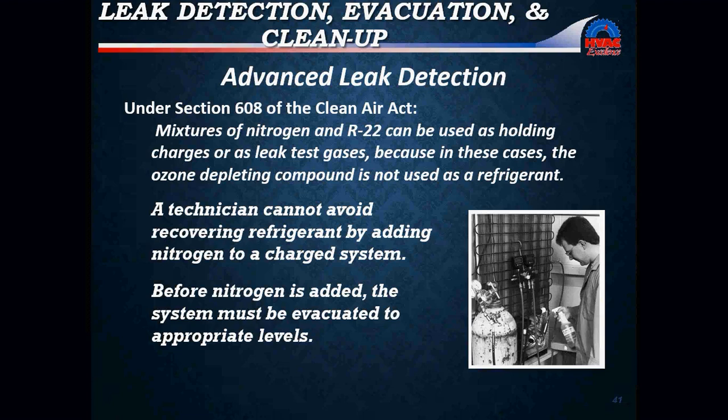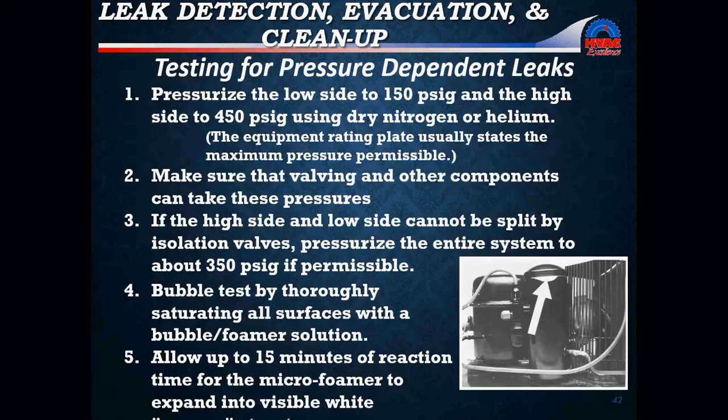The amount of R22 that's going to be introduced into the system need not be any more than that required for the detector to register its presence. That is per EPA. To ensure the 2 gases have mixed properly, bleed a minute amount of gas from the end of the system opposite to the point at which they were initially introduced. Okay? That is actually per EPA.